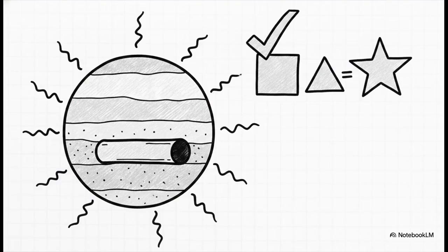And this works across totally different scenarios too. Using that exact same method, just swapping out the shape factor formula, we can easily calculate that a 15-centimeter diameter pipe buried in the earth loses 859.6 watts of heat. The geometry completely changes, but the elegant logic remains exactly the same.